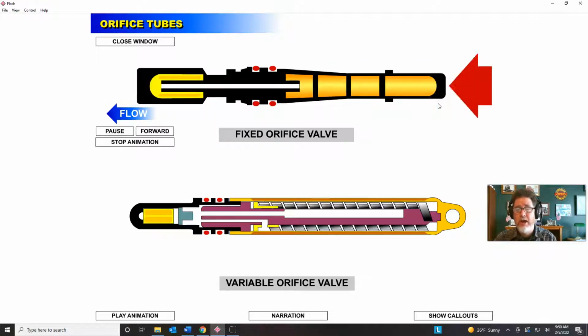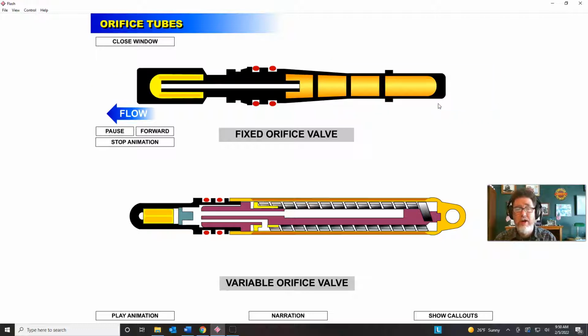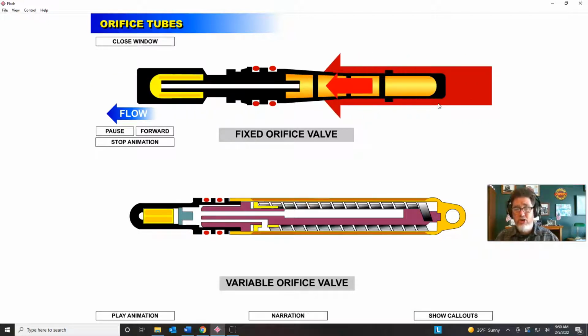and you have 2 different lines. You could put it in the line that is connected to the condenser 2 different ways, or you could put it in the line that goes to the evaporator 2 different ways. And you just want to make sure that you don't make a mistake and get this in backwards, because I have systems that I've taken apart where students have physically installed it backwards, so I've seen it. It can be done. So that's something to pay attention to as far as which way this should go.